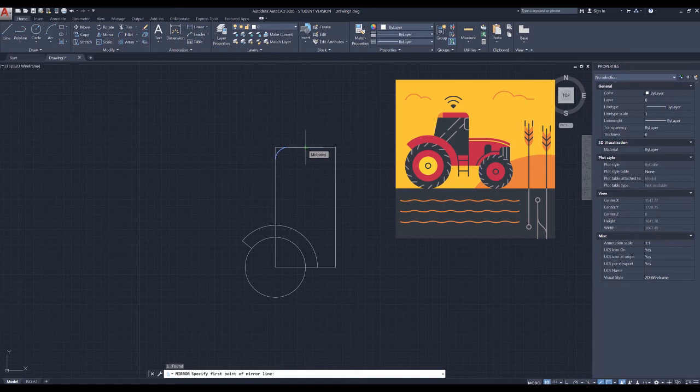So if I press the midpoint, okay, and start extending it down to create that mirror line, and just press out and press enter, okay? And now you'll see that I have the arc line exactly the same on each side. So this is looking really, really good.